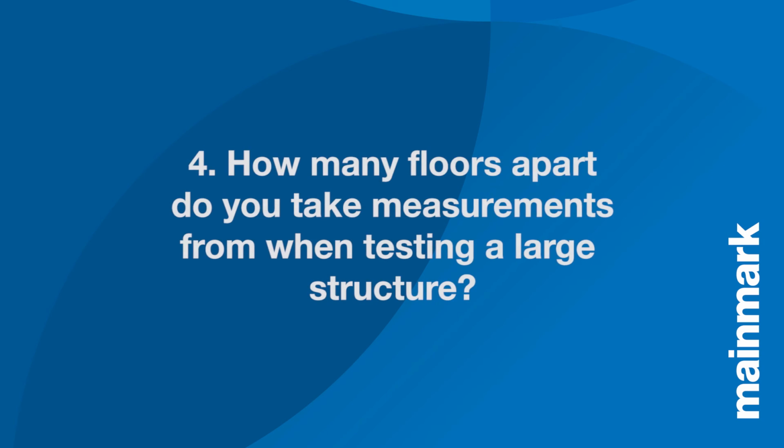It depends how large. Anything up to 20 floors, then we'll take every single floor. If we're talking 60 to 90, something like that, then we will choose the floors where there are nodal points, where it's moving from one phase to another, going through the neutral point. In other words, we'll take maybe every 4 floors at other levels, but at those critical points, we'll take every floor.